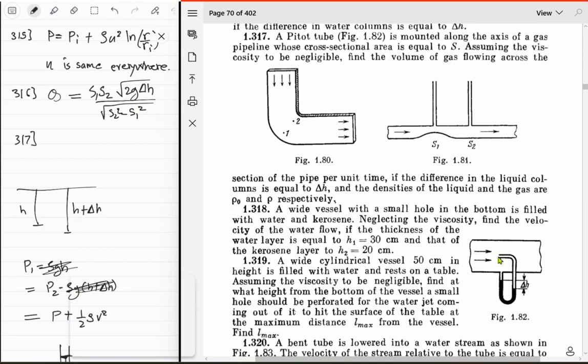And then the zero flow speed region actually comes out of the tube for some time. And then you will have viscous forces acting over there. So once again, Bernoulli's equation doesn't work actually. Huh, that was not good. But if Bernoulli's equation doesn't work, then how can you get the dynamic pressure? Because the way we do that is we rely on Bernoulli's equation. But if that doesn't work, there's no way we can say that the pressure inside is just the dynamic pressure. Or is there some way that I'm missing?